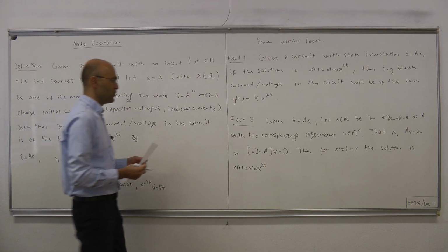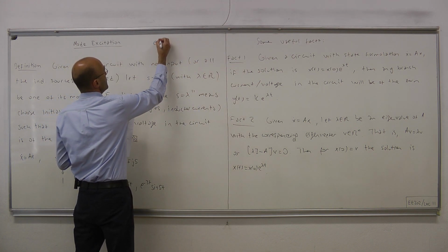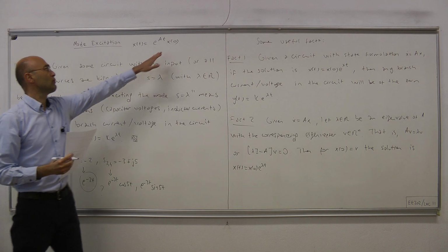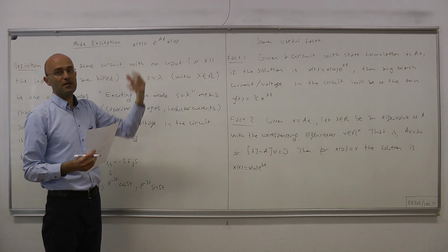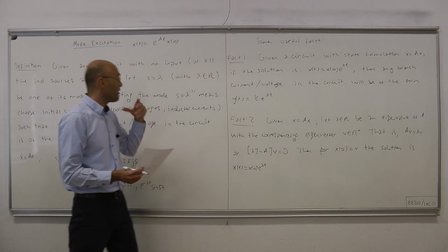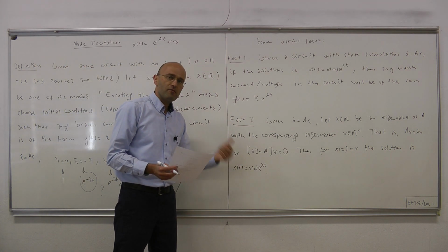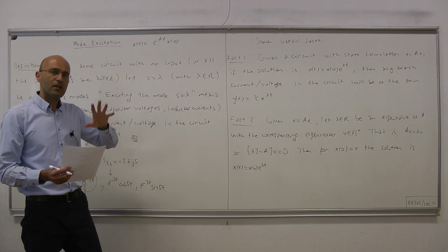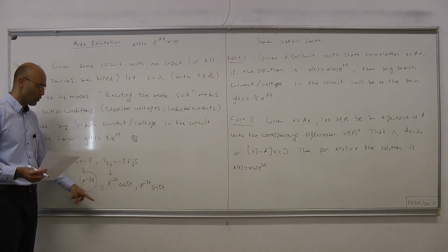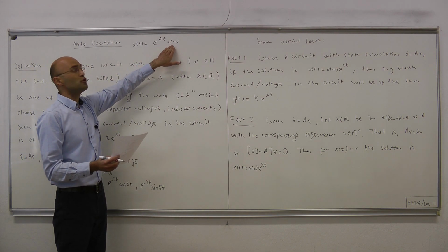Okay. Now, in general, we know that the solution to the homogeneous state equation is e to the At times x0, for any initial condition. Now, e to the At is the matrix exponential. It has many terms, and all those terms will be related to all the natural frequencies. Therefore, in general, this x of t will be quite complicated in form. It will contain all the natural frequencies. Okay, like here, a constant term, e to the minus 2t term, and those oscillatory terms.